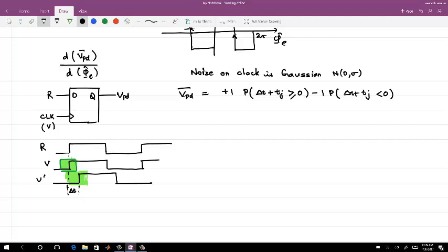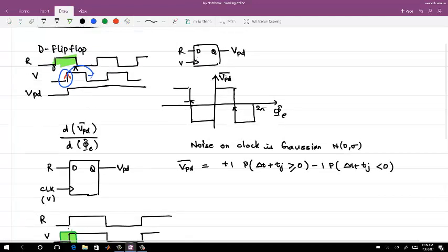So what we are calculating is that if you see previously, we are having a sharp change at T equals 0. If you are below 0, you are negative; above 0, you are positive. But think about it. If I have noise in one of these clocks, then whether you are below or beyond the rising edge depends on how much jitter is at the sampling point.